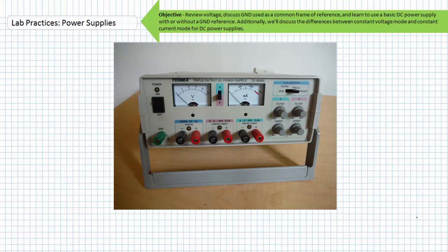If, however, I'm using the A terminals and my display selector switch is set to B, I have no idea what the A terminals are producing because I'm not reading them. Don't do this. You wouldn't drive to your school and look at your cell phone the whole time, would you? It's dangerous because you're driving blind if your meters aren't reading the terminals you're actually using.